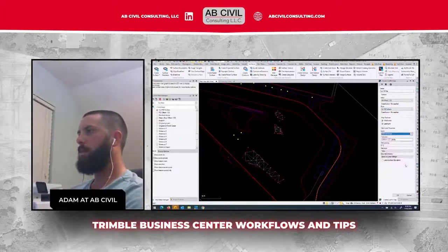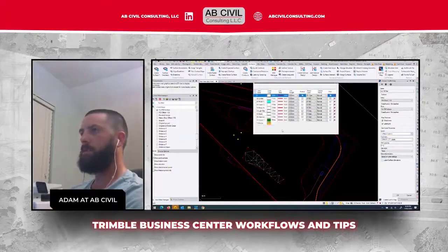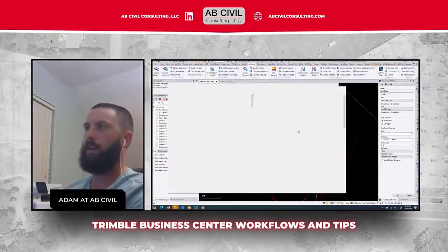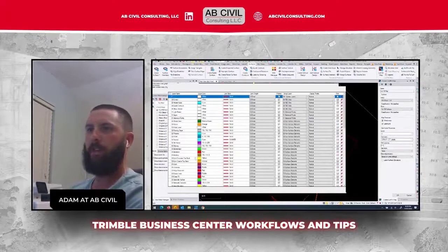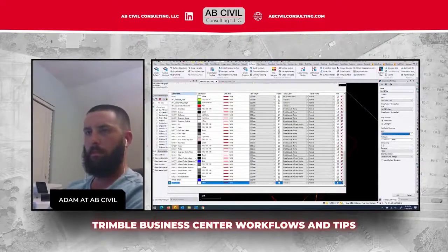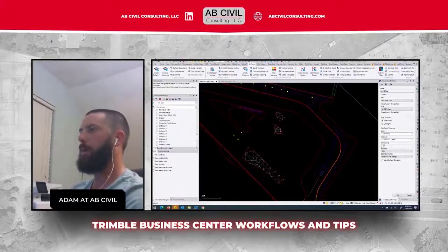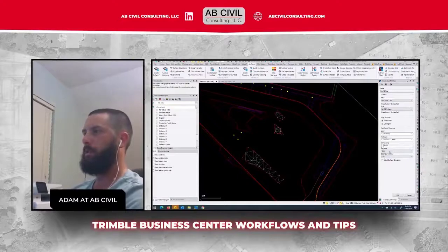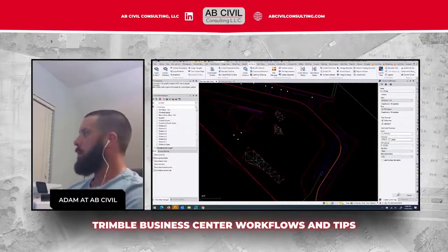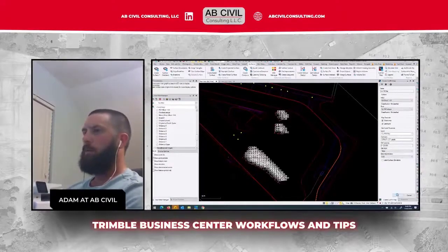I'm going to make a new layer for this. I think I already did a cut fill map here, so I've already got stuff filled up on that layer. So I've got the textile, cut fill labels, grid. It's going to be tough because they're so small, but let's see if a 5-foot grid will work. Do 0.12 as the decimal precision, and I'm going to hit OK.